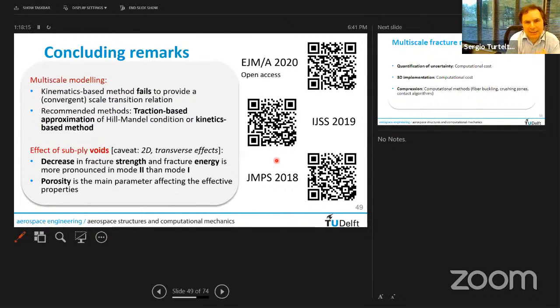It's a bit like plasticity. You could have a model for plasticity in rate form, which would be the proper way of doing it, versus thinking of plasticity in total form, where you give the amount of deformation and then figure out how much plasticity has occurred. That is not possible because you need to know the path. The same thing happens with fracture. You need to know how this has evolved, and it's not independent. So I'm rambling a bit, because it's an issue that has bothered me for a long time and is still bothering me. The short answer is no, basically. I don't know if that answers your question.